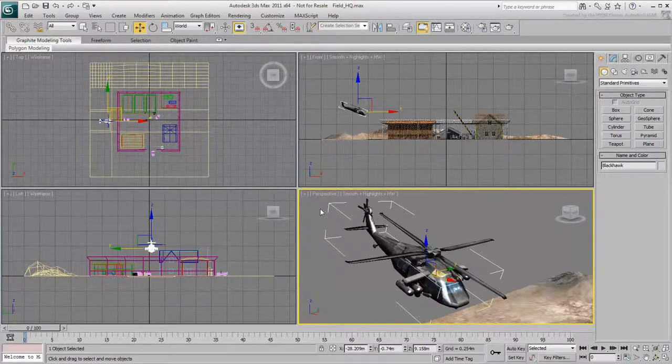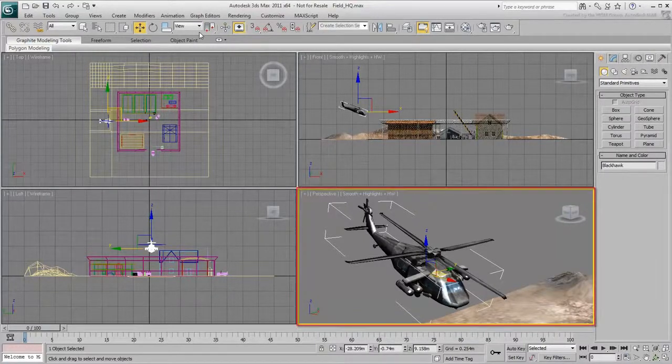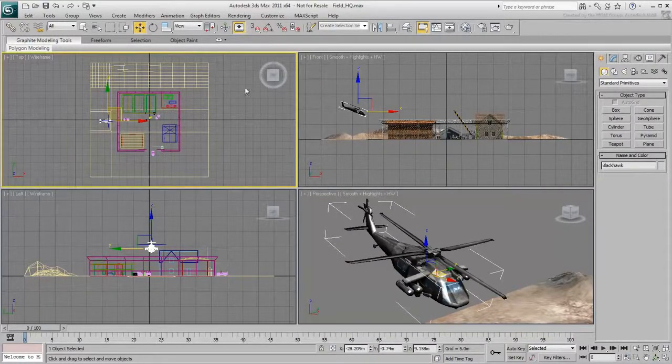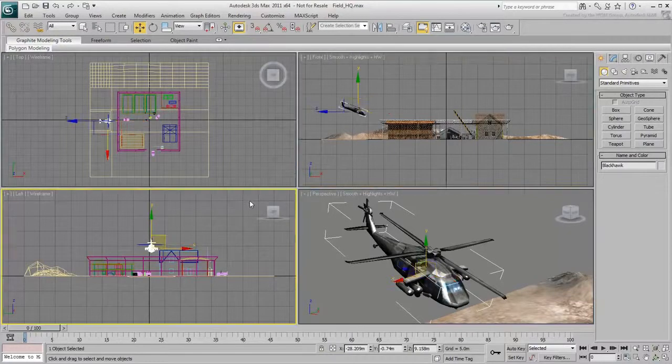However, using the world coordinate system in 3ds Max is not always the most productive way to work. As you transform objects in the scene, you're more likely to use the default view coordinate system. View works like world if the active viewport is a 3D view like perspective. But in orthographic views, the axis tripod reorients itself so that you're always facing the XY plane. This simulates working in 2D in an orthographic view, where the XY plane always runs parallel to that view.